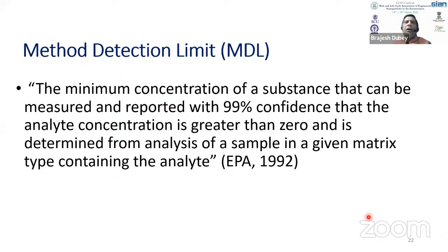Earlier, I said that the arsenic drinking water standard is 10 micrograms per liter. We all know that arsenic is a carcinogen. In the state of West Bengal, in several other places in India, in the country of Bangladesh, and in other countries like Vietnam, we are seeing arsenic pollution leading to cancer and all that. So why not put arsenic at zero concentration in the water? Why even go with 10 micrograms per liter? Let's make it 0 micrograms per liter. But the reason it is not zero is that you cannot really measure zero. You can have something below detection, but below detection does not mean it is not there.